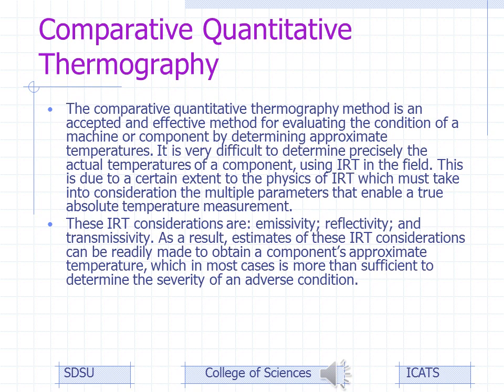This is due, to a certain extent, to the physics of infrared thermography, which must take into consideration the multiple parameters that enable a true absolute temperature measurement. Those infrared thermography considerations are emissivity, reflectivity, and transmissivity. As a result, the estimates of these considerations can be readily made to